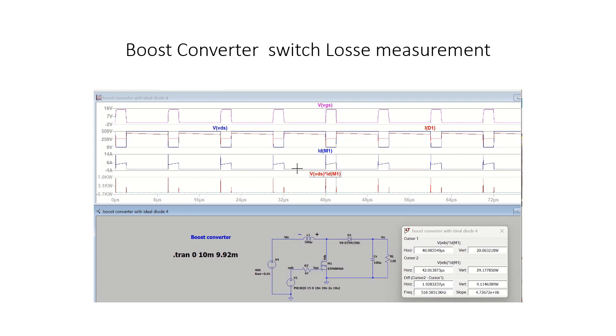Okay, so now we can see the diode current. And you can see that in the MOSFET current, there is a spike here. And you can see that turn on losses are higher than the turn off losses. Earlier it was the other way. To show the ID one, I just delete it for the time being.